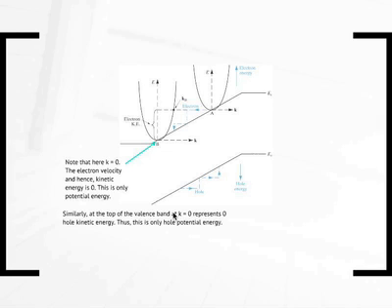Okay? Now, the simple band diagram is a plot of the lowest point of the conduction band or the highest point of the valence band as a function of space. Okay? In other words, the simple band diagram shows the potential energy that the electron sees as a function of location within a crystal. It's another way to think about it. Now, of course, the potential energy will change if you apply voltage, electric field. That's the definition of potential energy. The volt is an electric field, right?